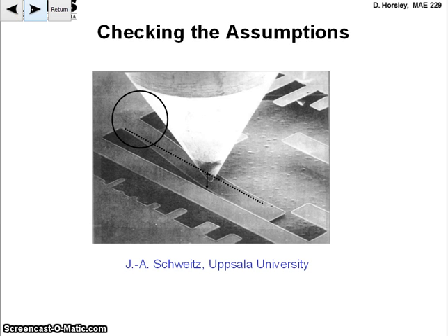And so here's a funny picture. Checking the assumptions: people have done mechanical testing of these structures. This is an example where they're bringing a probe down into contact onto this cantilever beam. You can see here, look at the base, right? It is indeed clamped. There's no curvature here, and so this support is really pretty well approximated as a clamp.